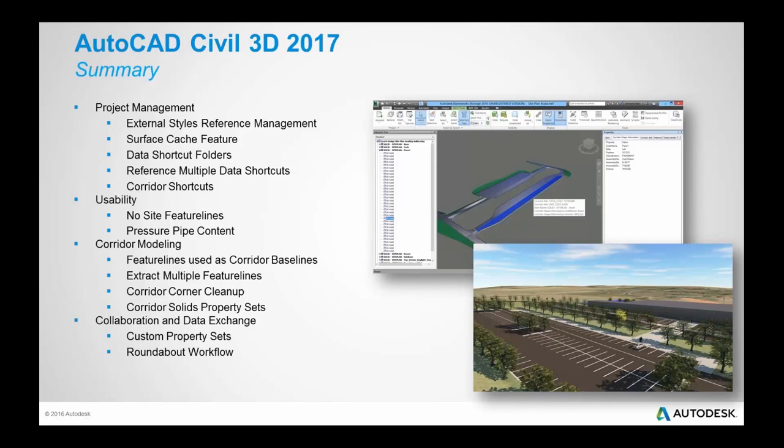Using Autodesk Vehicle Tracking, you can make a roundabout object. This is not the one that's been in there since 2010 or 11. That one is actually gone now. This is a whole new tool for creating roundabouts. Frankly, it's the most powerful tool set in Civil 3D if you're doing roundabouts, and this tool designs it the way you want. So certainly some caveats there.